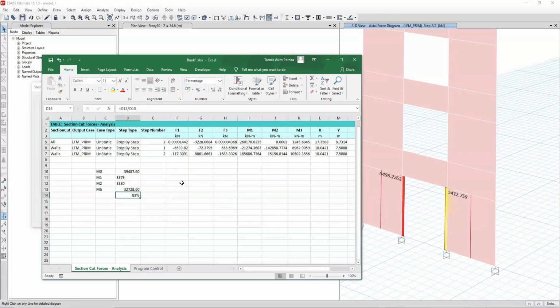Why? Because we are assuming that, globally, the moments would have to be the same. Without coupling, ignoring that stiffness might differ slightly, this total global moment would have to be distributed between the two walls. Since it isn't, because we have coupling, the individual moments M1 and M2 are much smaller. The reduction we achieved was due to the axial couple, which clearly indicates the degree of coupling. The larger the couple, the greater the reduction of individual moments in each wall. Now we will repeat the procedure for the central core.